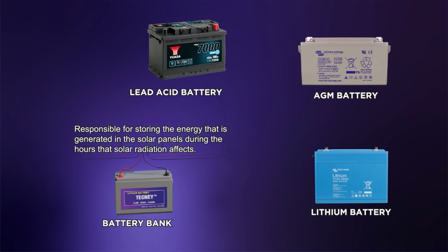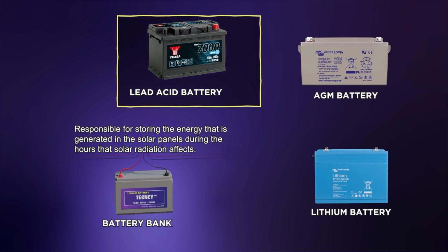There are several types of batteries, such as open lead-acid batteries. They contain 6 separate but series-connected compartments that are immersed in sulfuric acid. The plates that make up the battery contain positively and negatively polarized electrodes that alternate within the battery. This type of battery is normally found in cars. Discharging is only allowed up to 30%.